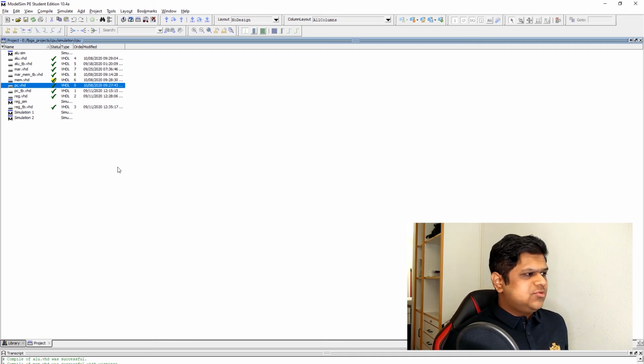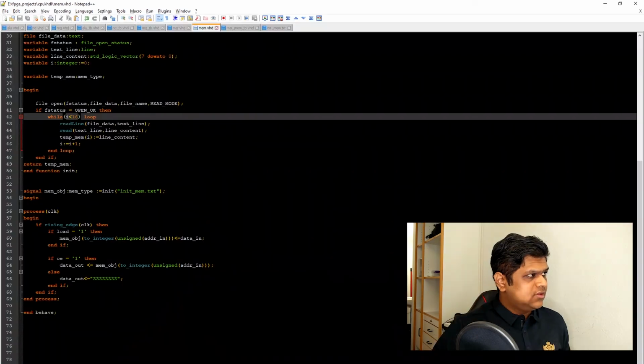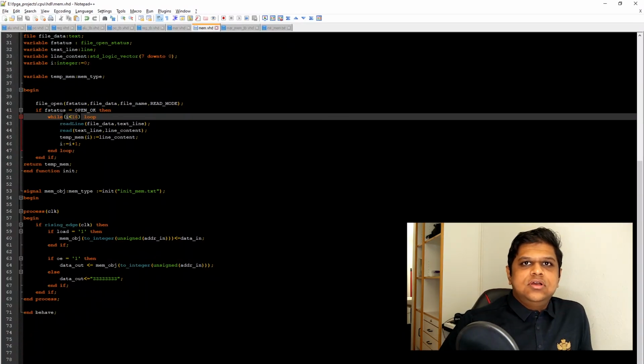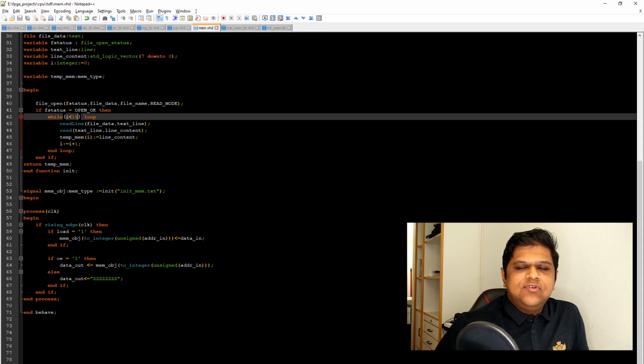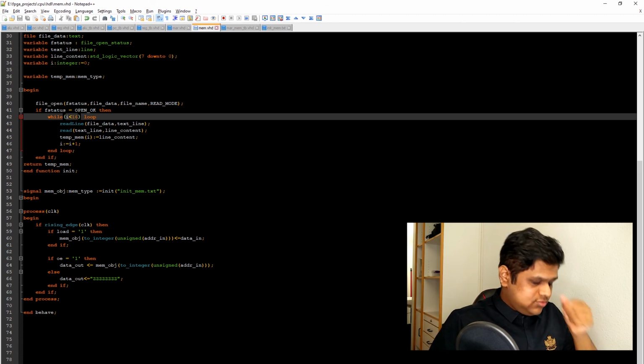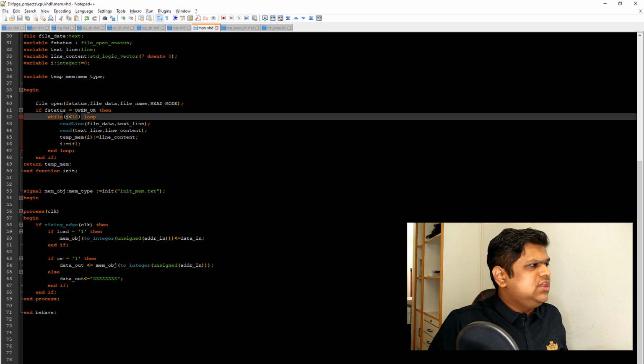I'm not sure what the problem is with the memory. If I figure it out, I will edit this video and add it to this. So for now, that is all. Hey guys, so earlier the memory initialization was not working. It was a really stupid mistake on my part. We need to store the file into the simulation directory and not the HDL directory. I was not aware of this, so we did that, and we ran into another problem.